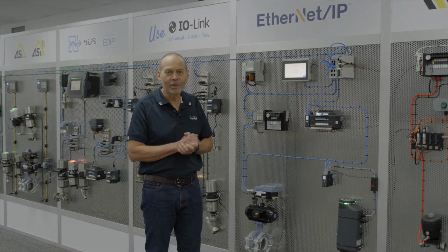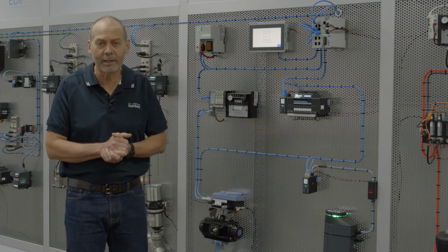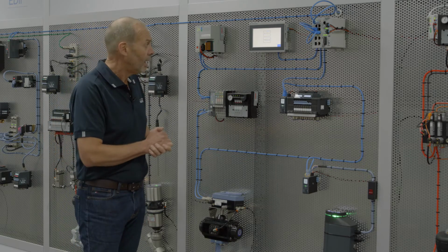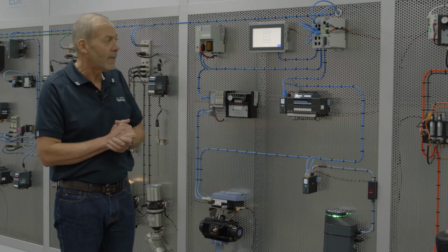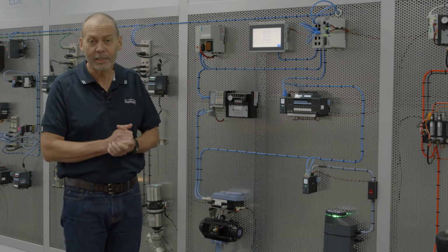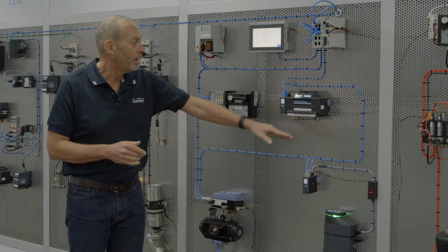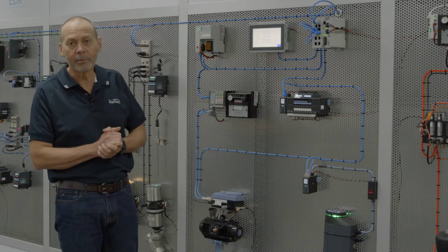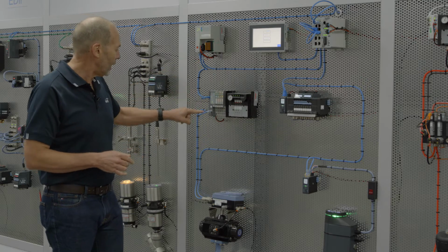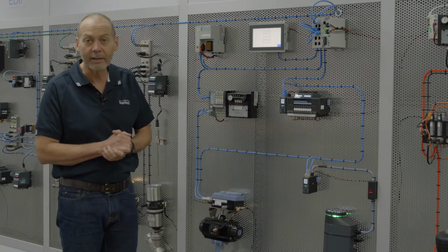Welcome to our digital connectivity video on EtherNet IP. EtherNet IP is also a widely used network protocol, and these days more and more it's being taken to the field. When it's taken to the field, we tend to use devices that are capable of running a device level ring, or a DLR, which is a redundant protocol which can hook up to multiple devices out in the field. So with a device level ring, you loop in and out of each device, and you come back and you close that ring at the other end.